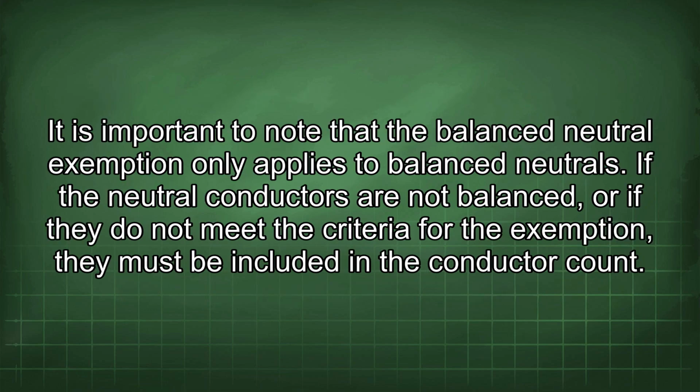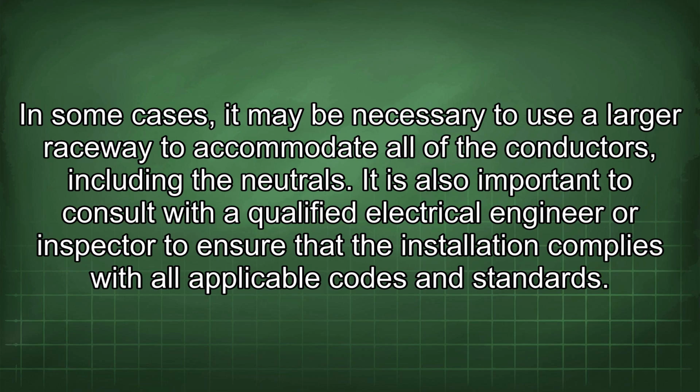It is important to note that the balanced neutral exemption only applies to balanced neutrals. If the neutral conductors are not balanced, or if they do not meet the criteria for the exemption, they must be included in the conductor count. In some cases, it may be necessary to use a larger raceway to accommodate all of the conductors, including the neutrals. It is also important to consult with a qualified electrical engineer or inspector to ensure that the installation complies with all applicable codes and standards.